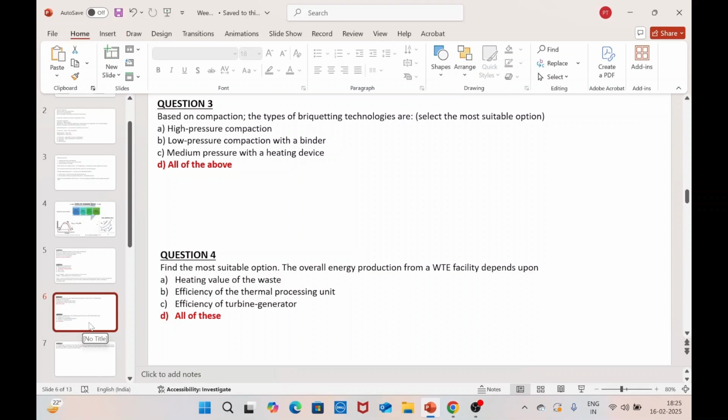We have discussed why moist conditions are not suitable for storing briquettes: if the binder is soluble in water, then it will get removed, and because of that fragmentation will happen. But to determine whether the briquettes will be suitable for moist conditions or not, there are certain tests which can be done. There are two tests in total. So does anybody have any idea, or can they describe it here?